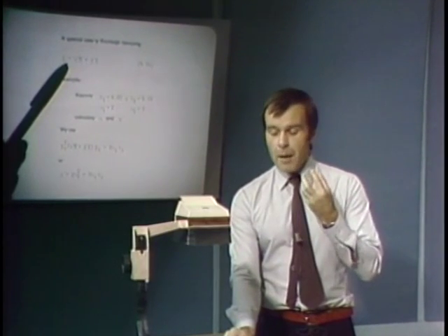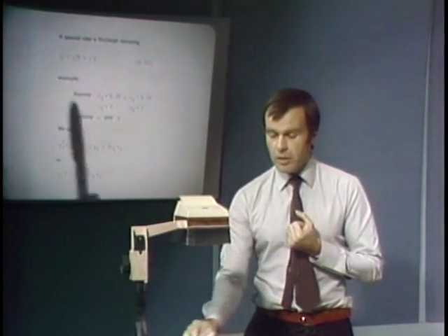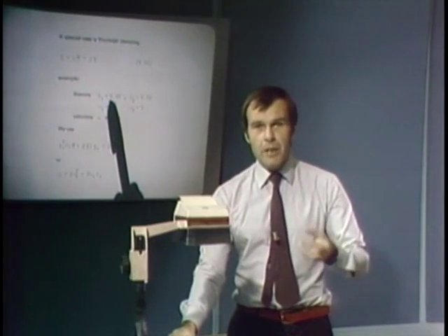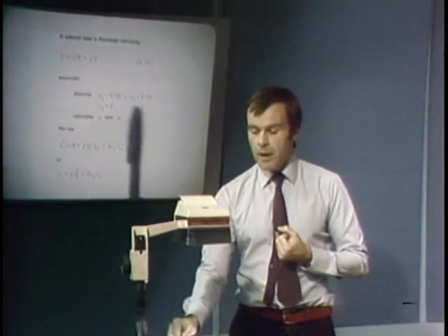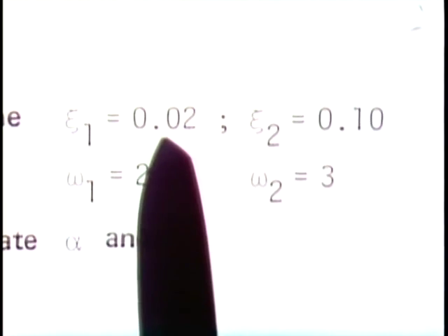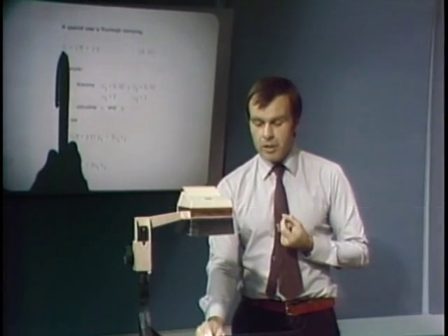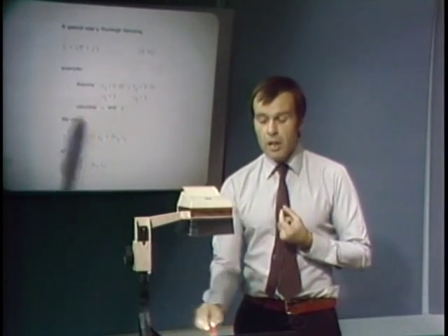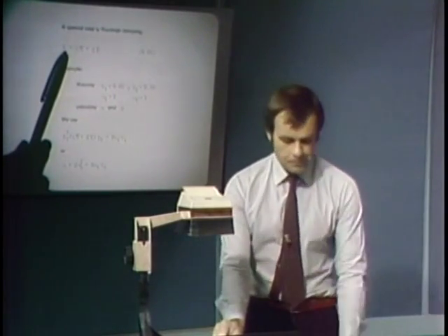You see, if we are performing a mode superposition analysis, we might know from experience, from experimental results, that psi1 and psi2 are of these two values. And then, if we know that we have so much critical damping, or so much damping in the first and second vibration mode, and we want to perform a step-by-step direct integration analysis, we would have to construct a C matrix. And this is a procedure to construct a C matrix.